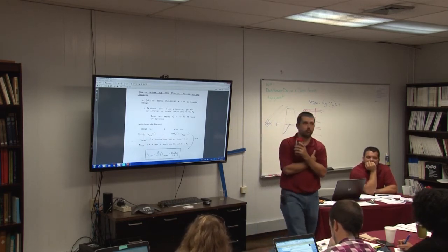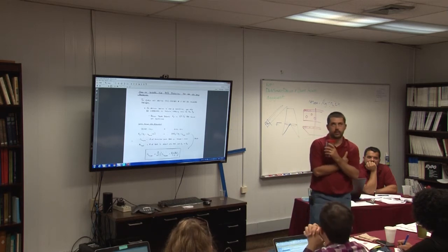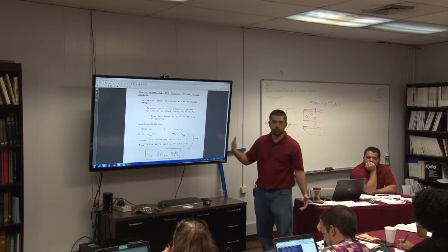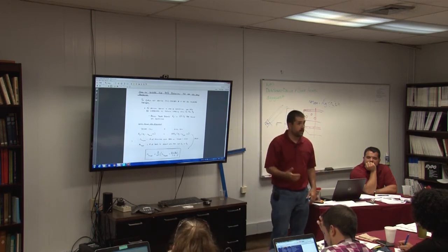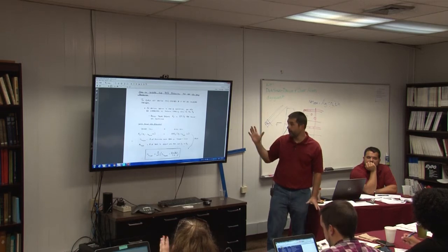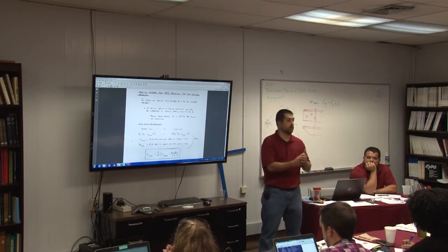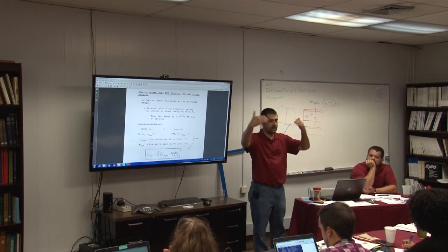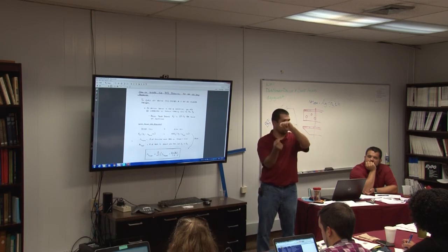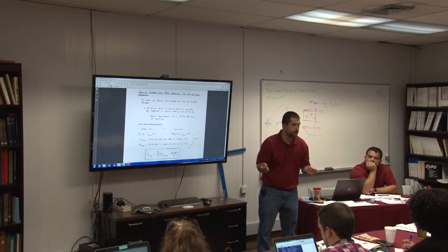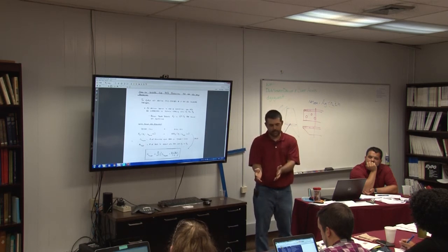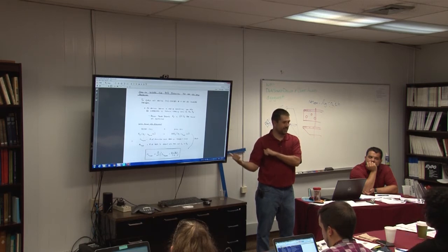The other thing, again, this is a very rare consideration. But if you have a member where your critical net section is mid-member, like we showed for the legs, but the member is only connected on one leg, so not a leg member, maybe like an arm on a tower, right? The arm is connected on one leg, but then maybe I've got a bunch of holes in the middle to connect to a bunch of bracing or something. So because you are telling the program it's connected on one leg, it's going to be using the 0.9 Fy in the net section calculation.